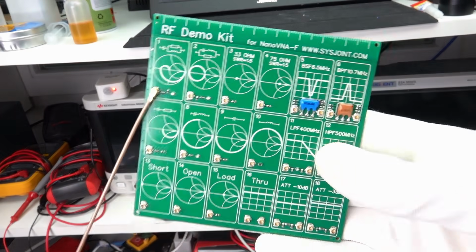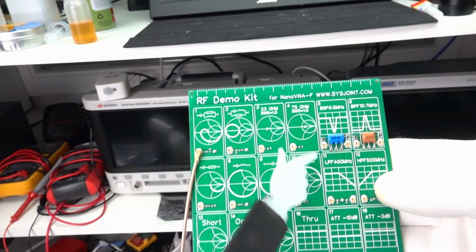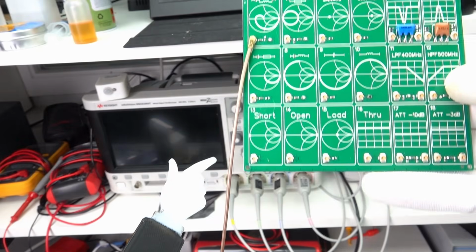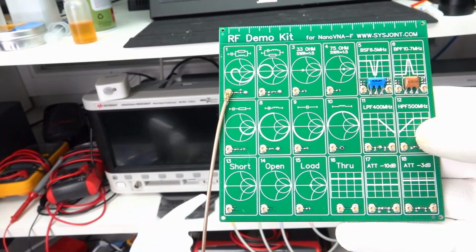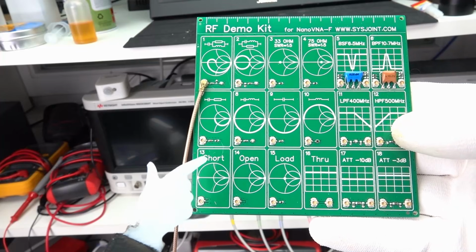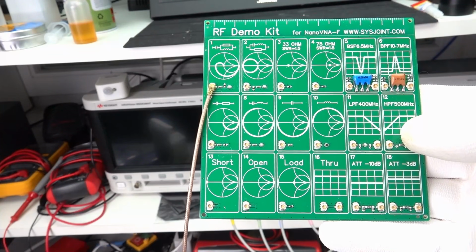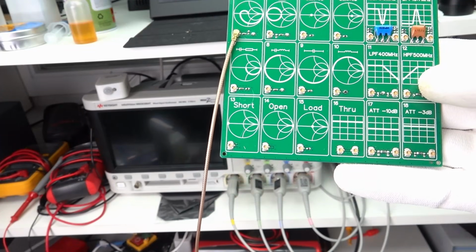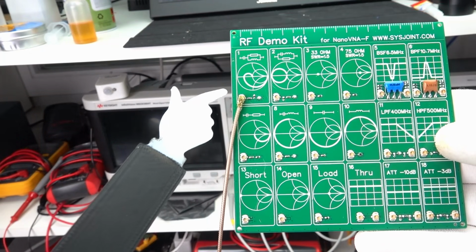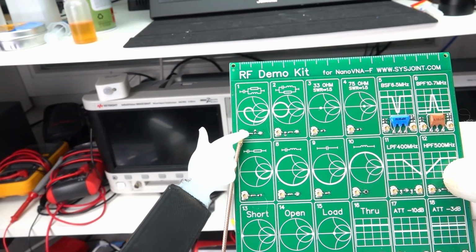The same but much worse applies if you want to measure on this demo kit, because you need a pigtail to connect the VNA to these tiny UFL connectors. Now we have 2 possibilities. Because the board has an open, a short and a load, you can calibrate on this board or use the port extension as before. Of course, with a much longer delay of 1.95 nanoseconds. Both establish a calibration plane at the end of this pigtail.